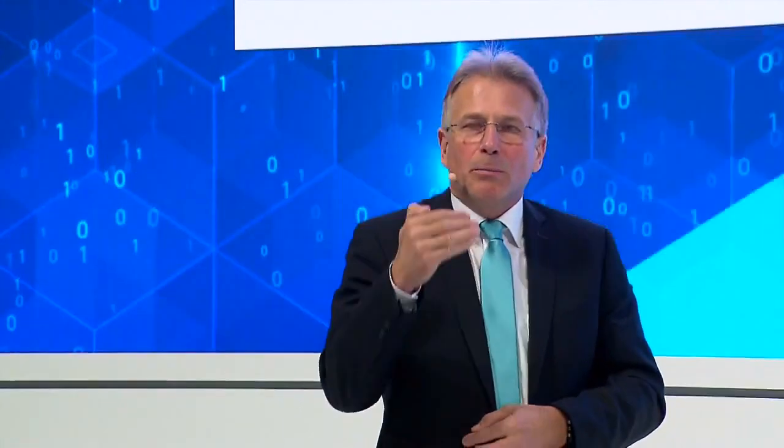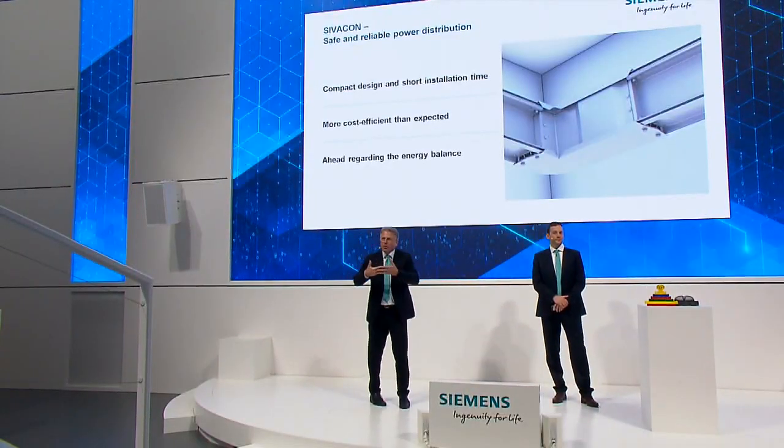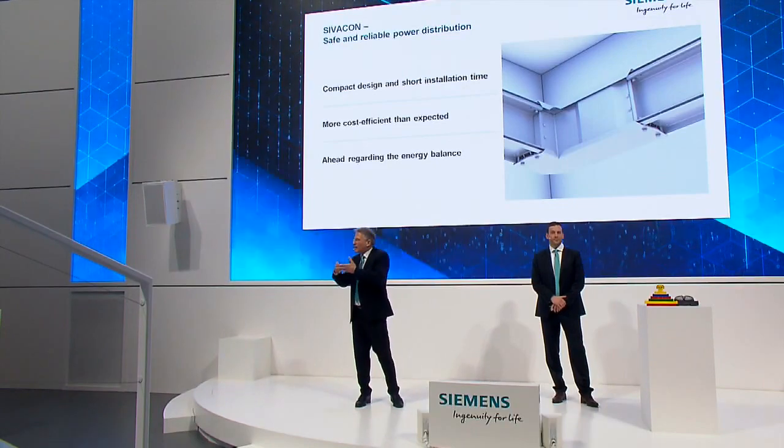With a busbar trunking system, you save space, that's clear. But you also save a lot of installation time and installation cost because of very easy to connect and pre-assembled system parts. It is more or less as easy as Lego. That sounds to me like a big advantage over cables.